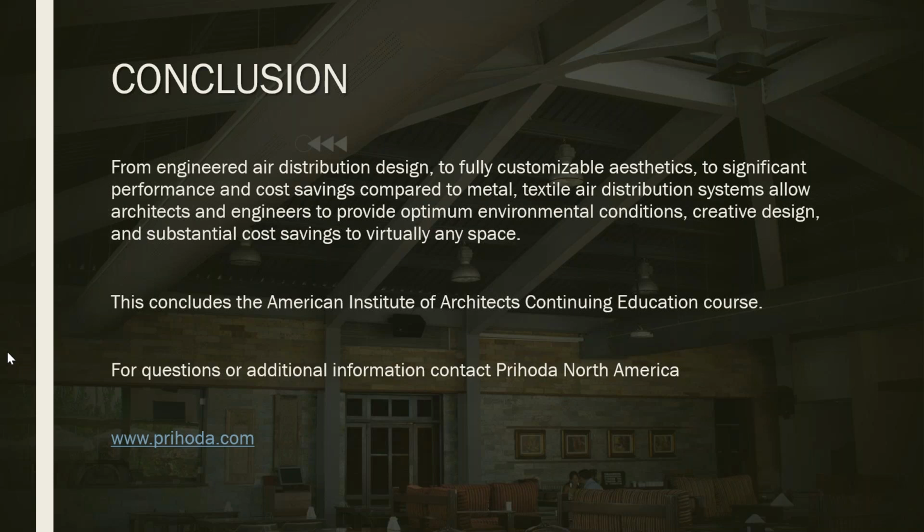First question was, is there a ULC listing for fabric duct? Yes, there is. Most manufacturers do have ULC listing also. Specific to us, yes, we do have ULC listing. I can't answer for every other manufacturer out there. The specific certification is CAN ULC S102.2, if anybody's interested, but you'll see that answer in your question and answer dialog box.